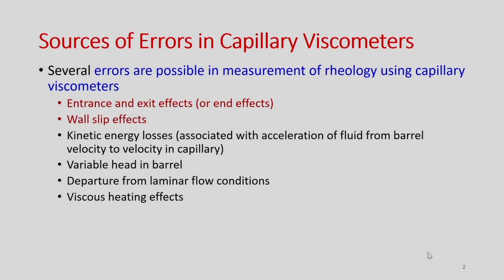If the flow is not fully developed, then definitely there will be a possible error. Experimentally, if the flow is not fully developed, that will induce some kind of error. If the flow is not laminar, you convert the experimental Q versus delta p information into the Reynolds number. If you see that the Reynolds number is beyond the laminar flow conditions, then whatever rheological information we get using the working principle developed in the previous lecture will also induce some kind of errors.